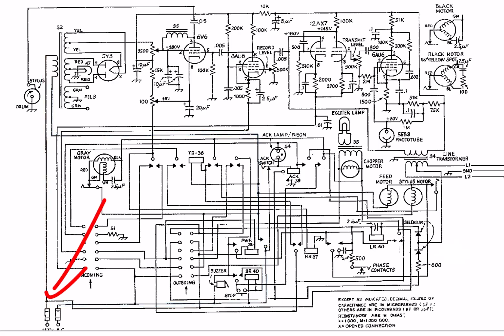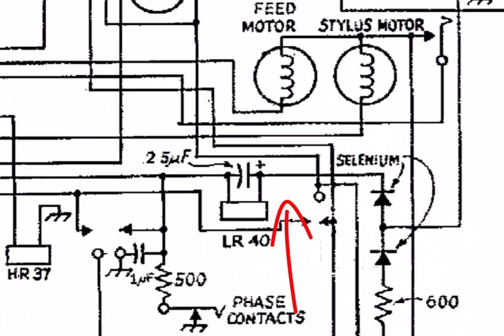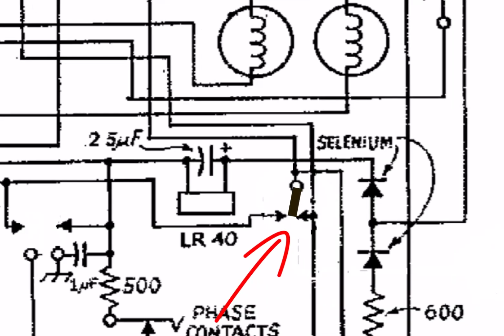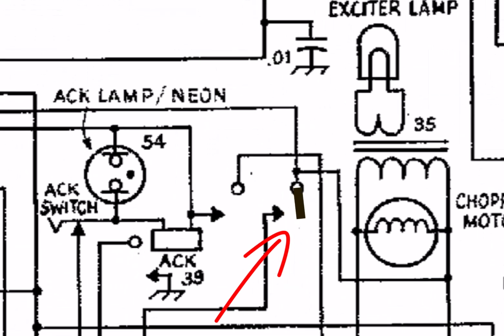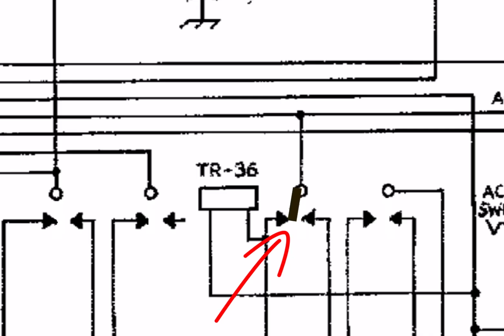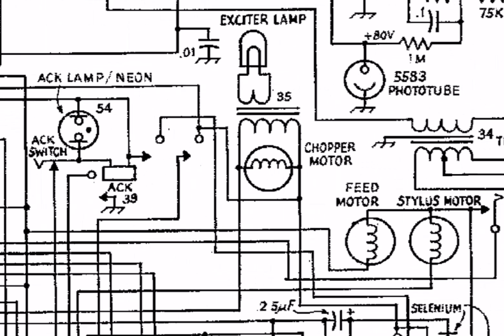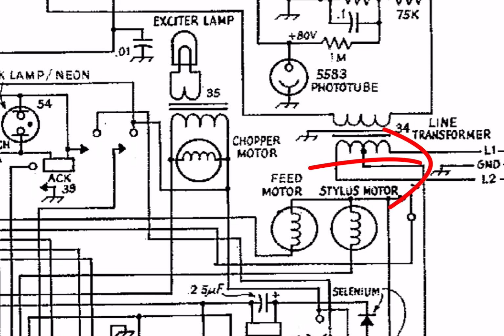But most other portions of the circuit have the second line input switched, which operates as an AND logic, meaning one button needs to be pressed and something else needs to occur before they're powered up. Now, there's no telling which of the inputs are line and which is neutral, because back then receptacles weren't polarized or grounded. Now, they did bring in a ground connection through the subscriber line connection, so this wasn't a floating chassis that you needed to try the plug put in one way and then flip it over if it either shocked you or if it had a hum.